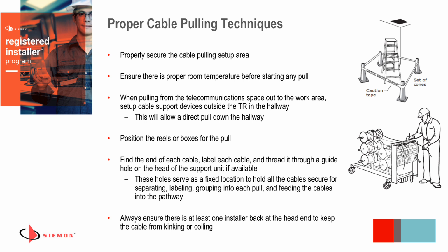Additionally, you want to make sure that the temperature of the environment you have is in compliance with the temperature of the cables being installed. They do have minimum and maximum operating and installation temperatures, and it's important to ensure that those temperatures are in compliance with those products to ensure that those cables will perform properly once installed.